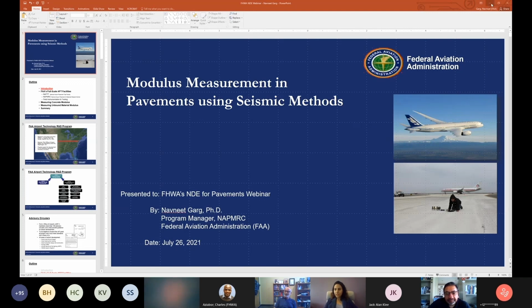Thank you. And another question is, what was the curing condition in the field curing and lab curing? Okay, so for the lab samples, we followed ASTM standard. You put all these beams and cylinders in a curing room where a certain humidity and a temperature and the moisture is maintained. Whereas for the field conditions, since the slabs were covered by burlap, we covered all our beams and cylinders also with burlap.